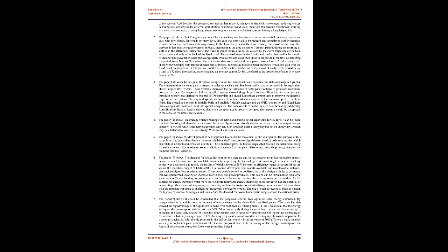Consequently, the energy efficiency of the PV system is evidently improved using the SMA tracker compared with the fixed PV system. In fact, the power efficiency of the proposed tracking system has increased about 39% for a sunny day. In case of unstable weather, the solar system remains safe due to the SMA actuators that surround it. As a result, wherever sunlight falls, it activates the part of the actuators facing it, which changes the inclination angle